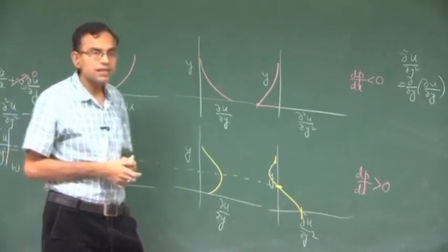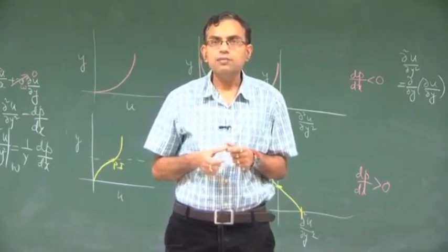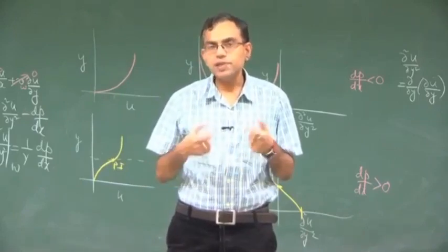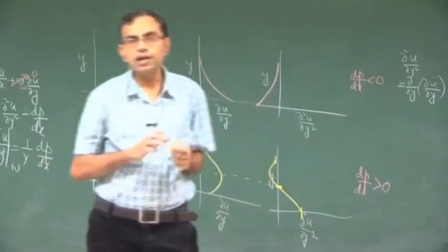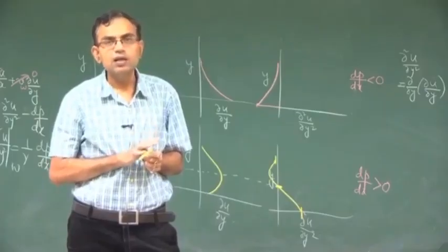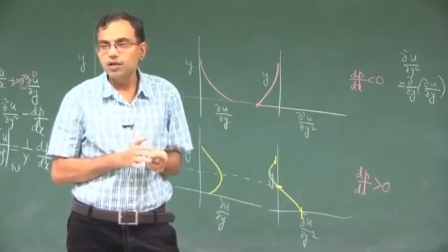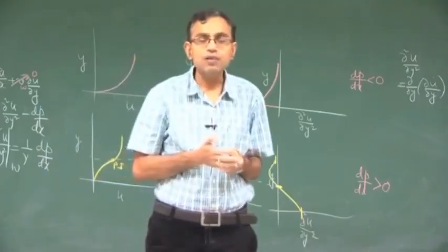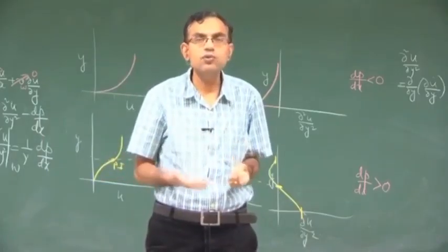So, to summarize, we have discussed the boundary layer in the absence of pressure gradient to begin with, and now in the presence of pressure gradient. We have identified that there are two types of drag forces, skin friction drag and form drag or pressure drag. Question remains that for different types of flows how these drag forces vary. For example, if the flow is not laminar but turbulent, then how this drag force will change.